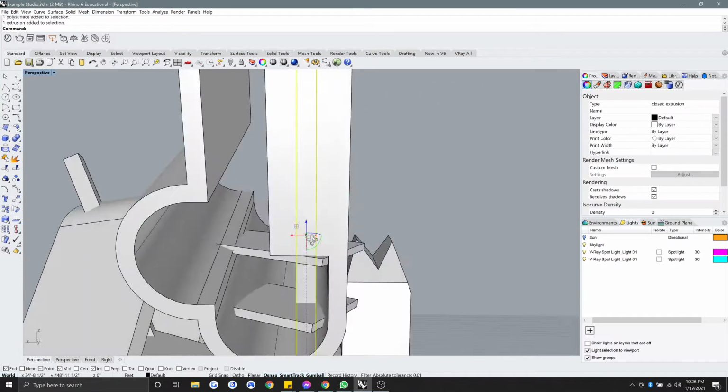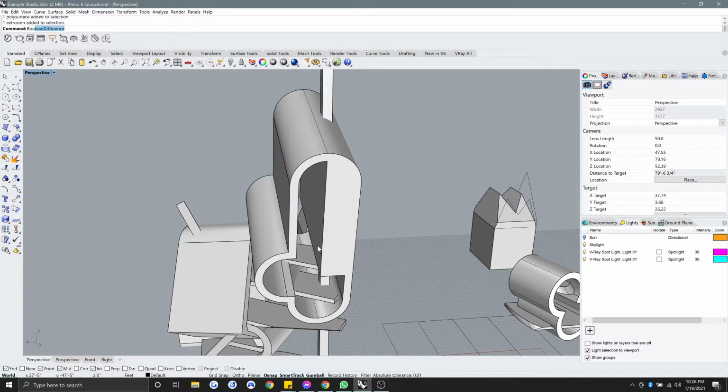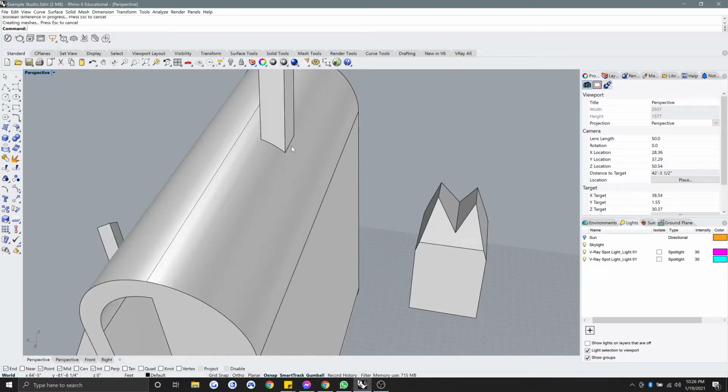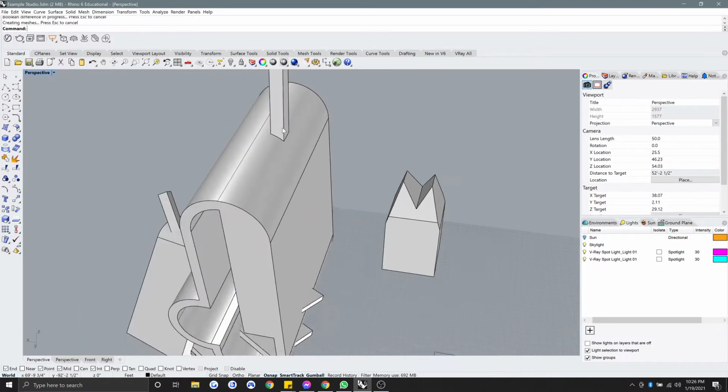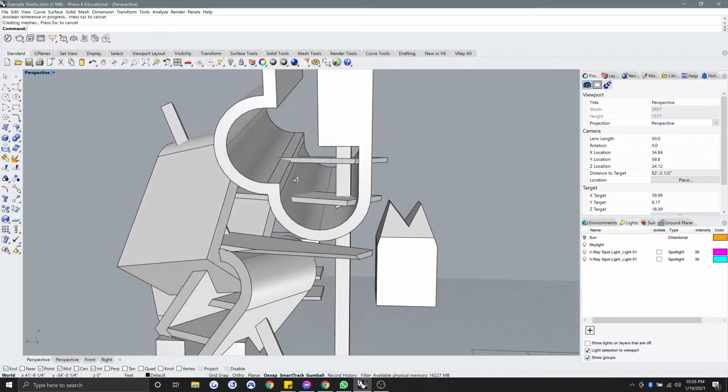I also have this support coming up through everything. I'm going to say that cuts through my object. So I'm going to cut this through there. Once again, we get these nice supports. If we hadn't done that, if I make 2D this, it's going to create a very strange edge right here. And the line weights aren't going to come through correctly. So modeling cleanly like this will make your drawing substantially easier to do. So I'm going to subtract from this piece again, because I had undid it there for a second.